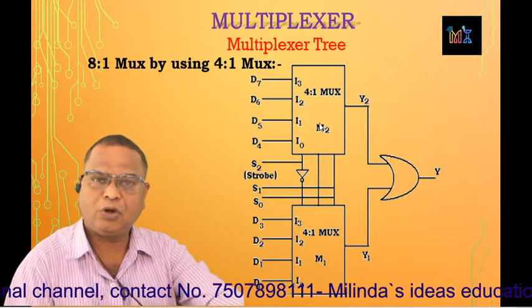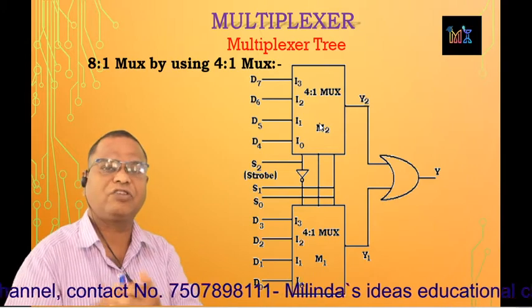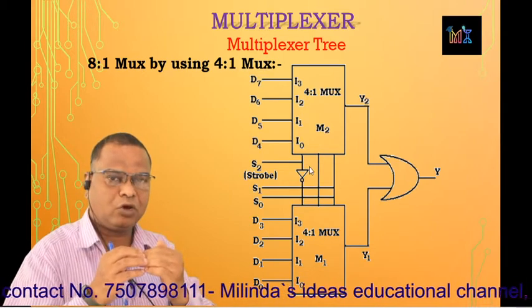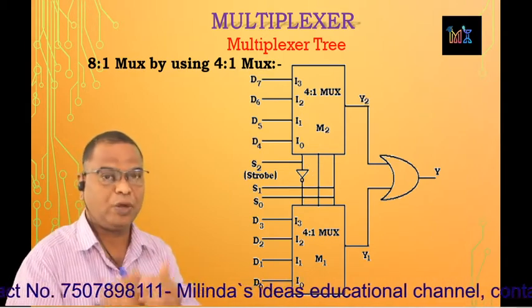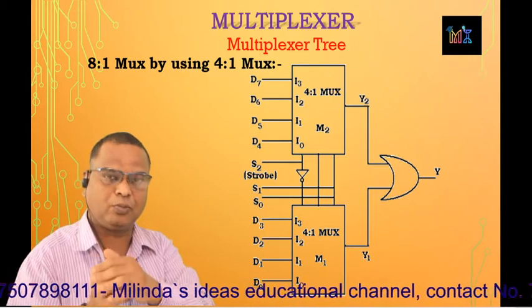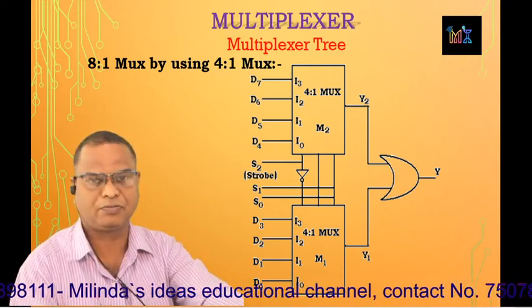The control input S2 is connected to the strobe input of the lower mux through a NOT gate. So the strobe input for the lower mux is now the complement of S2, while S2 is directly connected to the strobe input terminal of the upper mux.